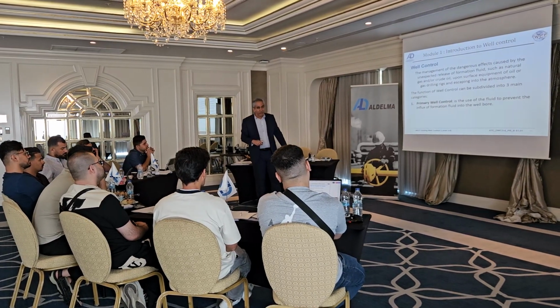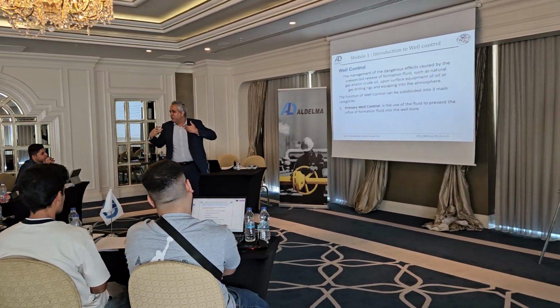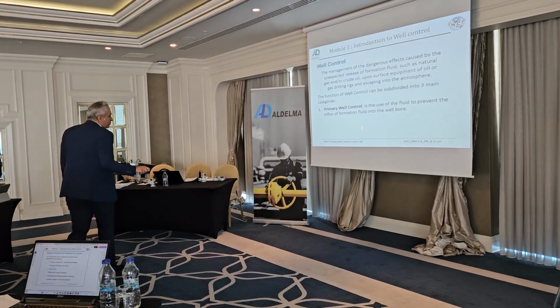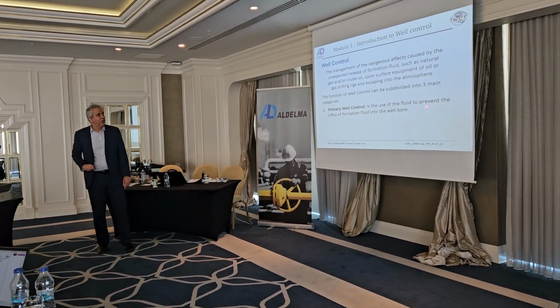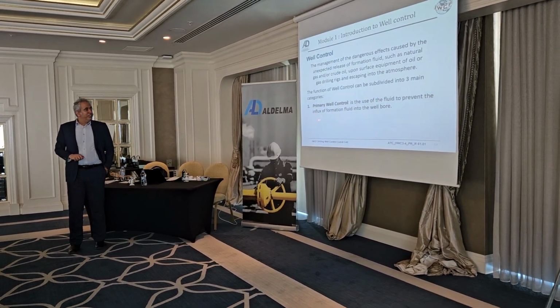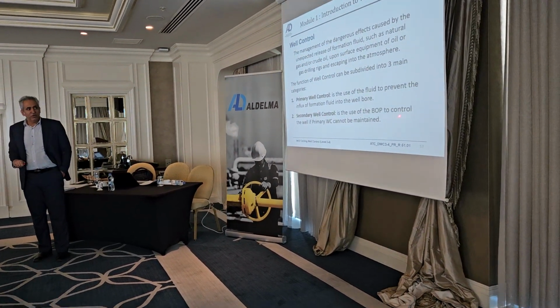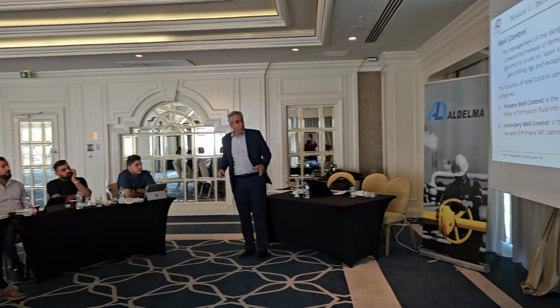If you look at the well control, now we want to see, okay, what is the well control? We have a primary well control, a secondary well control, and a tertiary well control. Primary well control is the use of, we talked about this, hydrostatic pressure, yeah? Use the fluid to prevent the influx of the formation fluid into the well. Secondary well control is the use of the BOP system, including not only the BOP, but the accumulator unit, all the connections, kill line, choke manifold, everything, flow line, all coming together. All the degasser, we need to look at all together. And tertiary well control is going to be squeeze, back cementing, relief well, yeah.